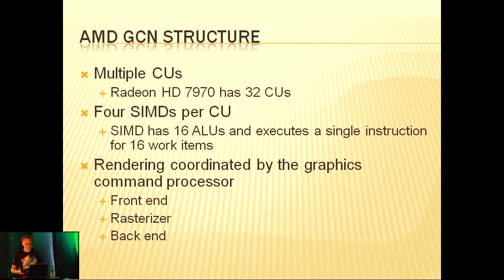The SIMD has its resources as well. One point about the resources of the SIMD, they're basically separated into two groups: shared and private resources. The private resources are the ones that the SIMD owns, so they're not shared with any other SIMD. They're the instruction buffer, registers, and vector arithmetic logic units. Then there are shared resources, like the front end, which controls the execution, the back unit, branch unit, and the data cache.